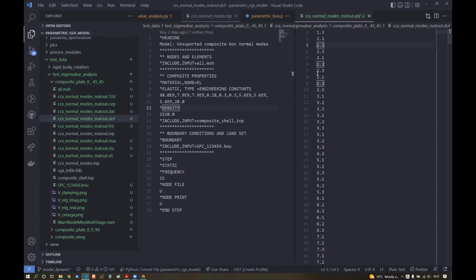So what we'll do when we do our aeroelastic analysis, when this file gets read, to define the eigenvectors for the aeroelastic analysis, we actually take an average of the deflections of repeated or duplicate degrees of freedom. So this basically gives you a lookup of the nodes with respect to the CCX model, and how those nodes match up with the rows of the stiffness and mass matrices.